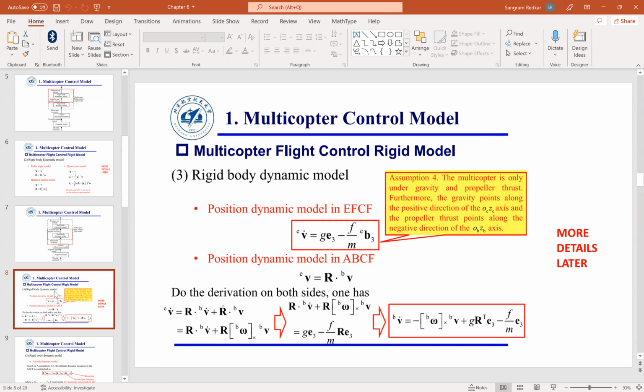But what I want you to understand is, at the end of the day, the first equation that I have shown you is nothing but Newton's law, force is equal to mass times acceleration. And this comes in the picture because you have the gyroscopic effect. You have the aircraft that is not going in only the straight direction, but is going straight and turning. That's why you are going to get the product of omega times v. Those types of terms will come in the picture.